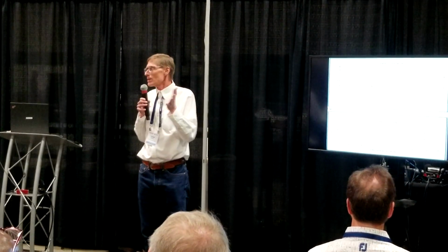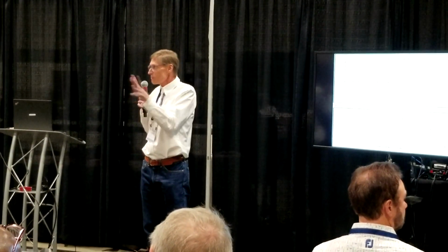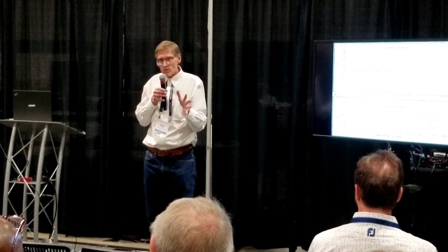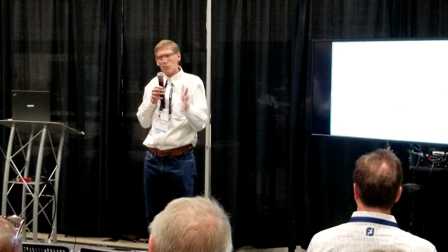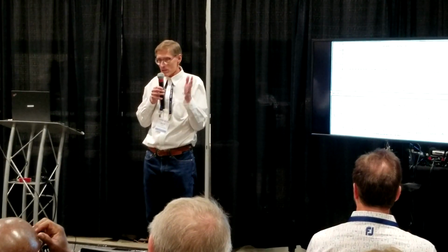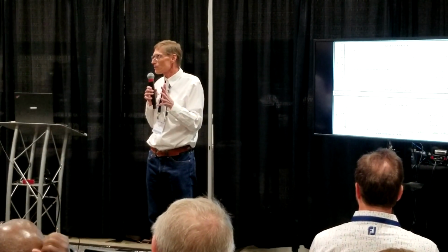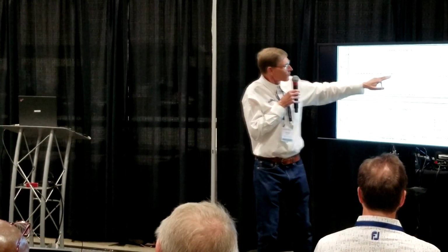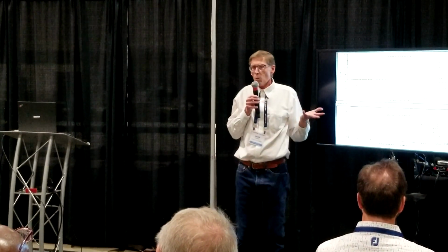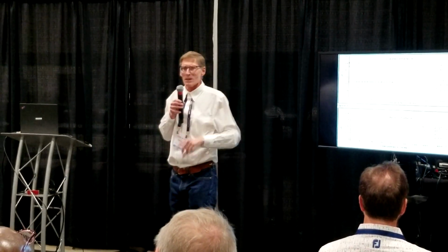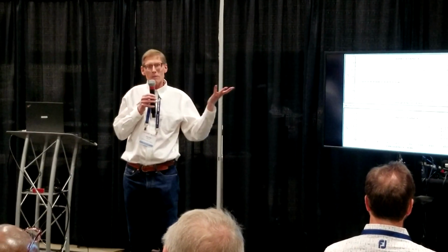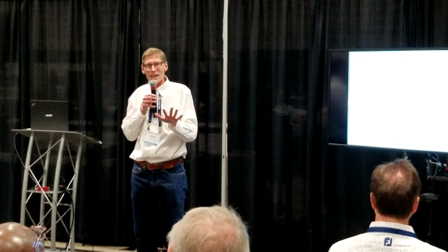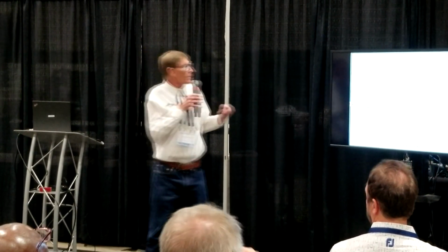Well, first of all, it was developed for MIL-C17D, the mil specs that you oftentimes use when you build cables. But in the old days, they used to use tubes. Tubes do not like to run RF reliably. It takes a lot of energy to run a tube at high frequencies. So the guys said, you know, capacitance is the same with respect to frequency, so why stress our equipment out? Let's just measure it at 1K. Now today we could measure at 1 megahertz or whatever, no sweat. But in the old days, the standard was 1K, and we've just kind of stuck with that.